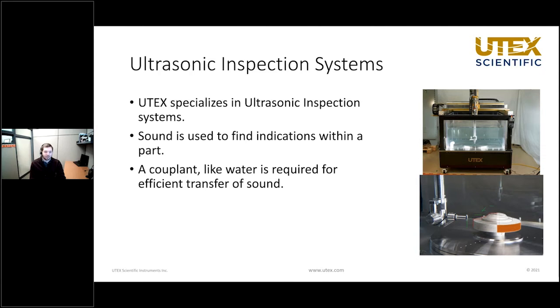Because sound is a mechanical wave, it requires a medium in which to travel through. Air is actually a poor medium for ultrasonic waves, so a couplant is required, the most common being water. This means our systems typically consist of a motorized gantry system over a large tank of water. However, in some cases where parts can't be fully immersed, a squirter system is used where a jet of water is sprayed at the part, and the sound is sent and received through that water stream.